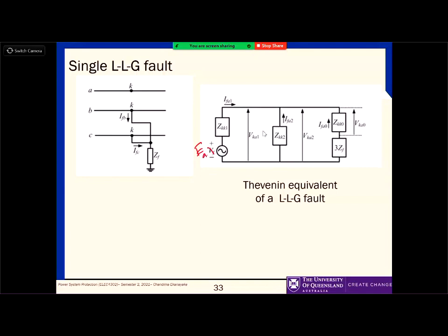Okay, so you can prove it the same way that I did. Put the conditions, as an example, in this case you can say that IA is equal to 0 and then VB, VC is equal to 0, right? Because VB and VC, they are short circuited and grounded, right? So once you put all those conditions and then rewrite those matrices, you will end up with this.